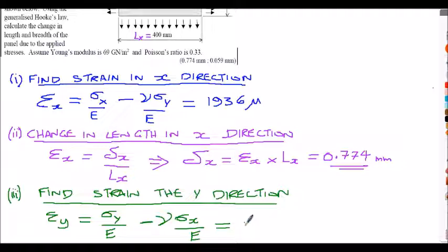If you go back to our tables we looked at on the previous slides, they were slightly different in the X and the Y directions, in the L and the T directions, but they're only just slightly different. So it kind of saves us having to use different values in the two different directions if we assume isotropic homogeneous. In this case, the E is the same throughout. So 394.2 microstrain.